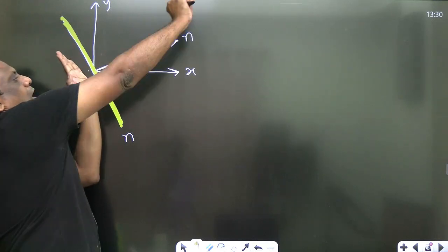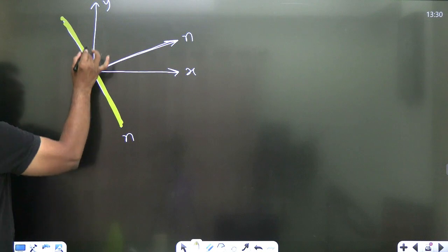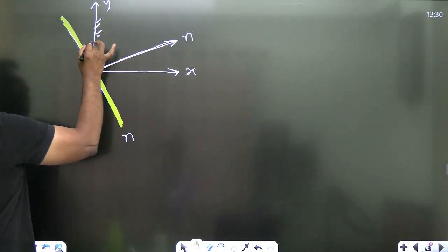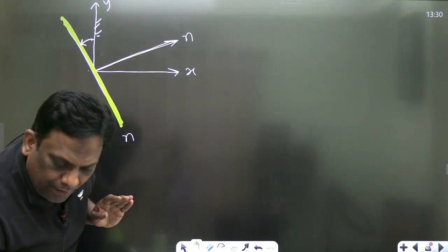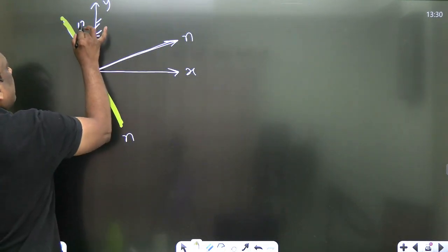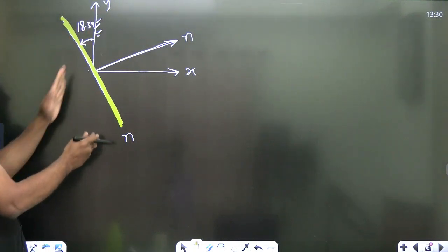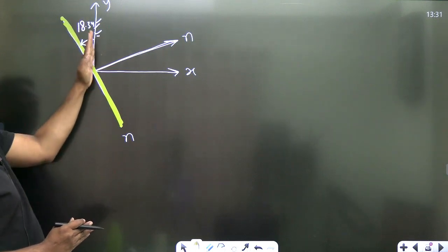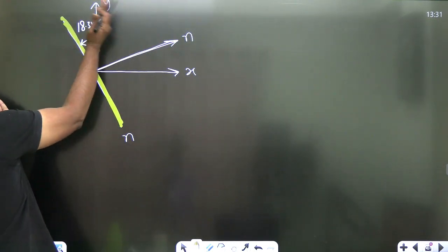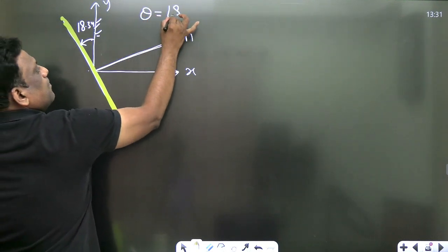On this plane this is the normal strain. So what will this angle be? You know, with respect to vertical, what is this angle? This angle you have just calculated, 18.34. And what is the direction? With reference to this, at what angle is this plane oriented? It is oriented at anti-clockwise 18.34. So I will write theta is equal to 18.34.